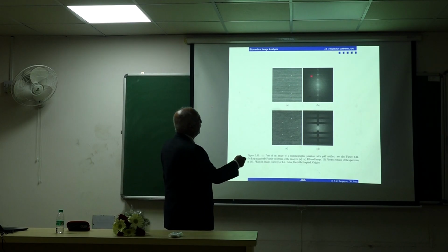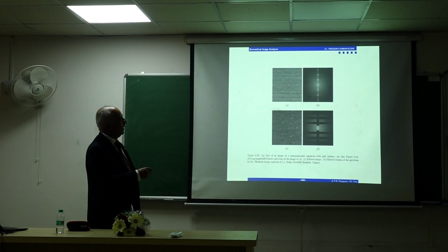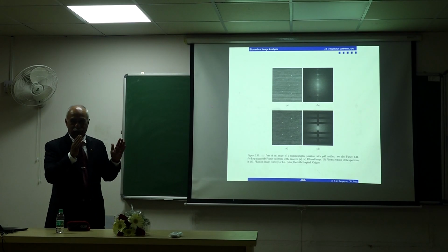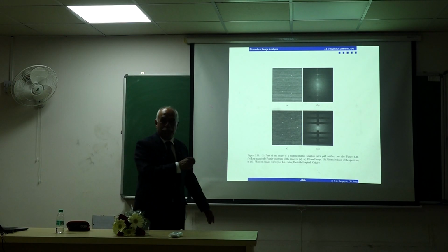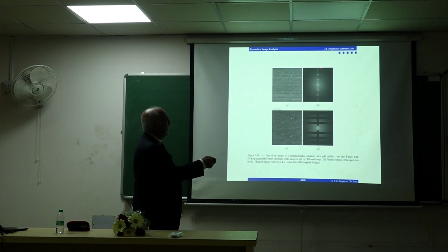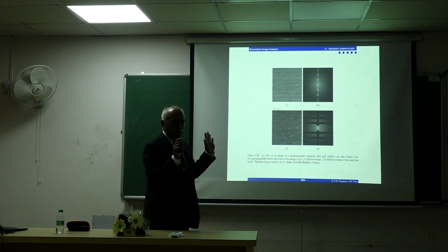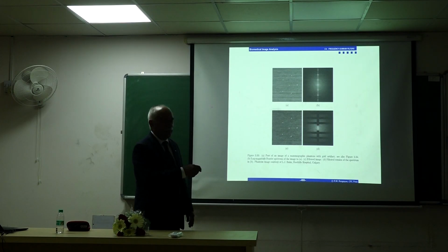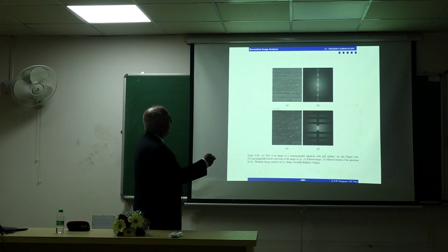There is also smearing this way, which could be due to aliasing or could be due to the fact that I'm using a finite window to compute the Fourier transform. Otherwise, you should only see these spikes. So to remove that, I thought, well, I'll just punch out those spikes and set to 0. That's not a good filter, but these are the regions I blocked out. A very bad filter. But I want to show you the artifacts also that are caused by the filter.